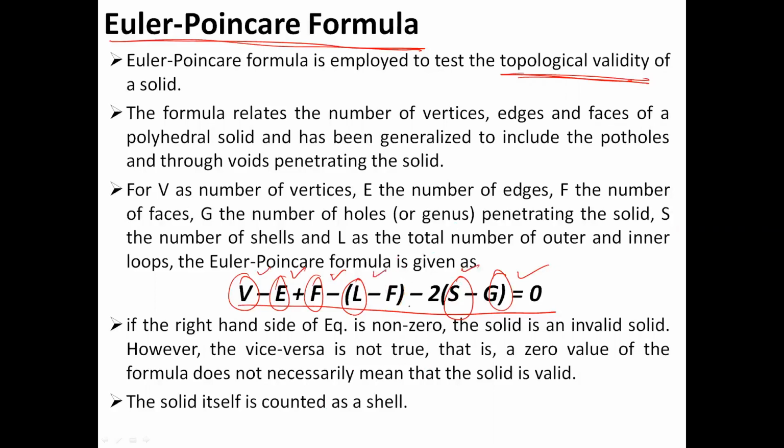So what is a loop? Loop basically stands for orientability. The loop is basically defining the orientability. If a particular face that you have constructed with the help of vertices and edges is orientable, then the number of loops on that face will be equal to 1. Okay? S basically reflects a solid, which basically means that the whole object is a single entity. So that is the formula for solid.